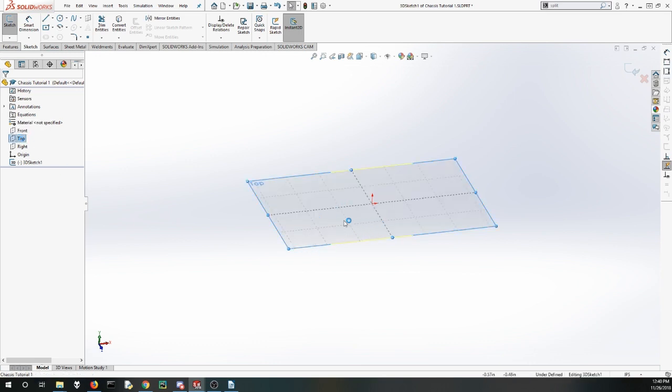When you double click, the appearance of the plane should change and it should have these grid lines on it. The reason you want this is because when you have the grid selected like this, you can only sketch within the grid, and everything is automatically constrained to that grid.